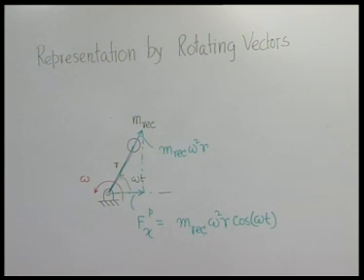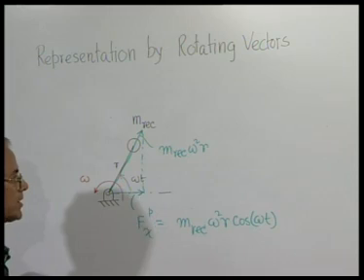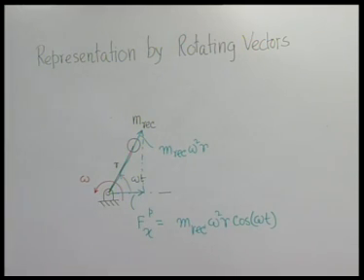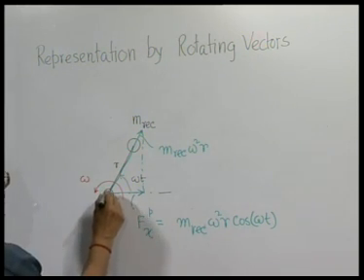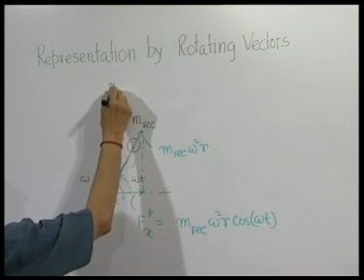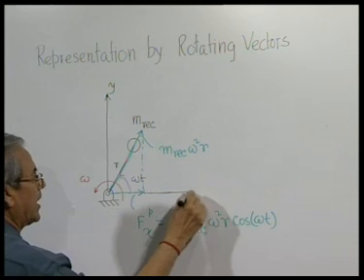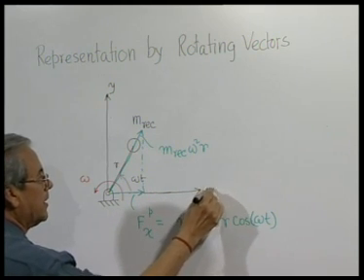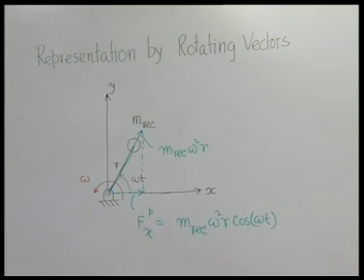Of course, we have to keep in mind all the time that it is only this component along the x direction that is really existing. The cross component in the y direction is not existing. Now, this will be useful only when we solve problems with multiple cylinders or engines and try to arrive at results employing the same kind of techniques we have used in rotary balancing.